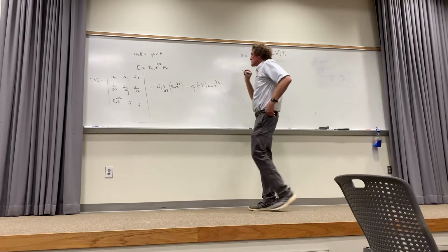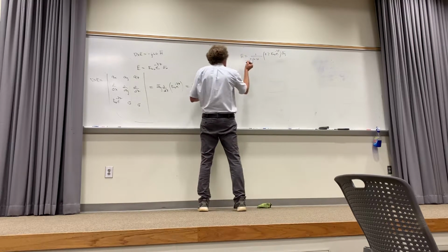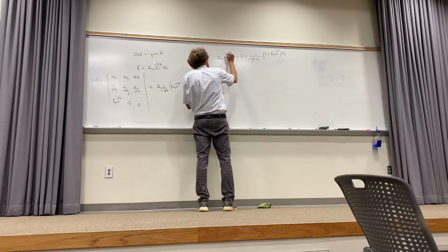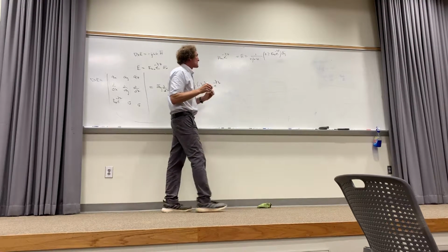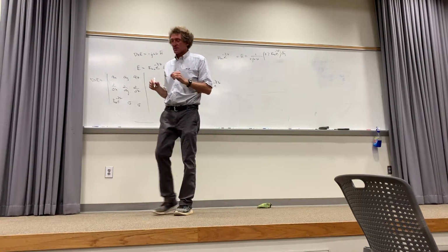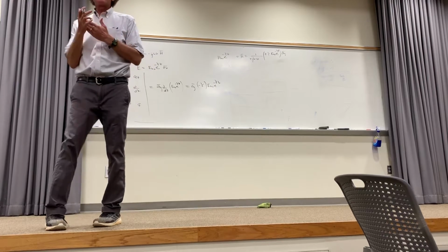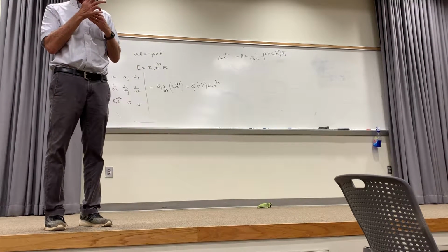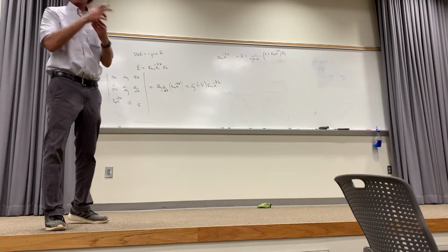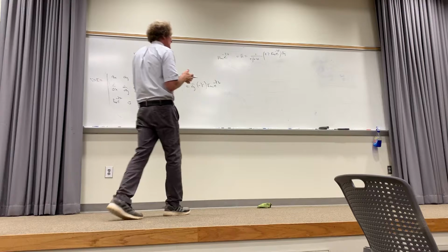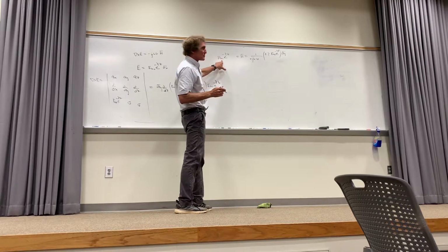And now I have this. Now, let me tell you one other thing. This will be some value HX0 e to the minus gamma z. It has to have the same, the actual same rate of change in z as the E field. The two are married together. You can't separate them. Where an E field appears, so an H field appears if it's time invariant phenomena. And that's just the way it is. And this is normally how we express it.